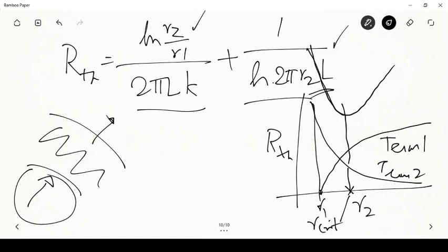Okay, why is that happening? Because this term decreases because of increase in radius, and below R critical that dominates over the increase of this one. Beyond this R critical, what you expect is happening the way it should happen. You increase the radius or you increase the insulation, and the resistance is increasing. So this critical radius can really be critical, because we think that we are adding insulation, but actually we are increasing the heat losses. But it can also be a blessing. Let us understand how.